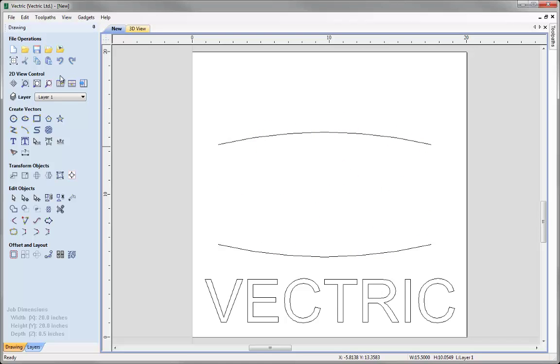We can also use this tool option to distort between more varied curves. So we may want to go into node edit and then maybe transform this into a Bezier span, and then maybe even insert a point here, and then use the control points to add some curves to this. So I'm going to escape from the node editing, and I'm just going to highlight this curve and press delete.